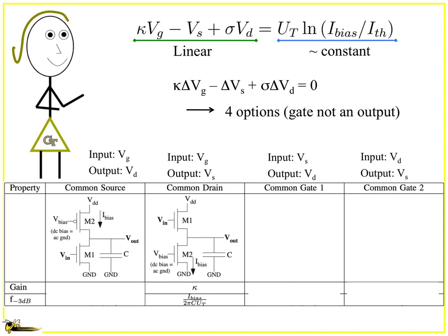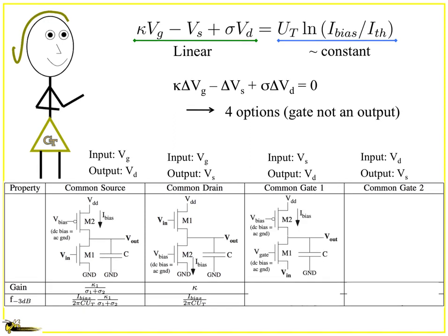I could look at a common source element, which, so for the common drain one, most people might believe that, yeah, I could see that being linear. The common source one, you solve the same way, and it's still large signal linear. And it gives you quantities you, by the way, would have solved for had you done a small signal analysis.